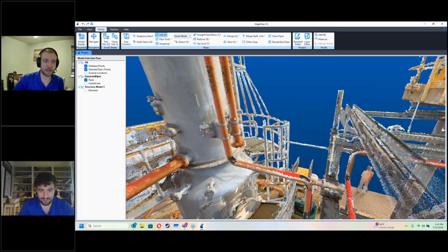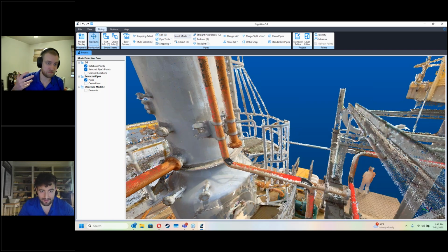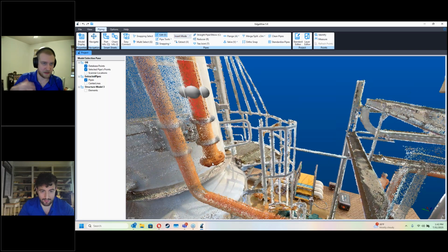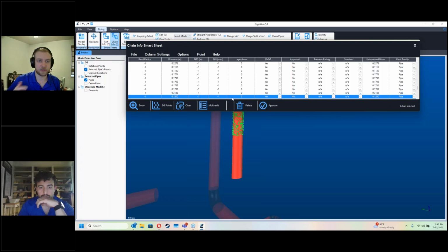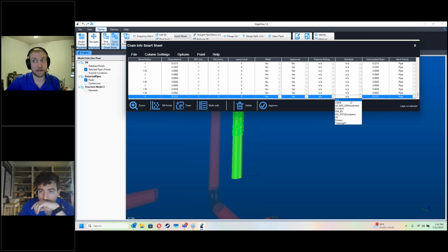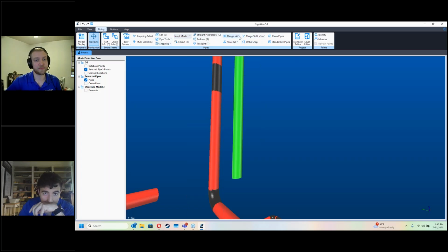When it's imported into Revit, it will be a generic valve. It'll have gate valve and other types of things like that, flanges, butt weld, and all the standard definitions there. And in Revit, Plant 3D and E3D, we will generate the geometry for those, and basic spec information is needed.